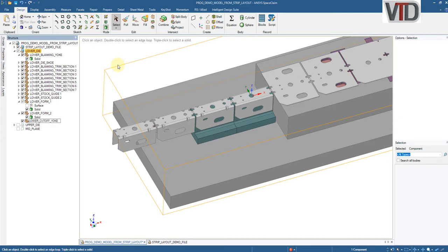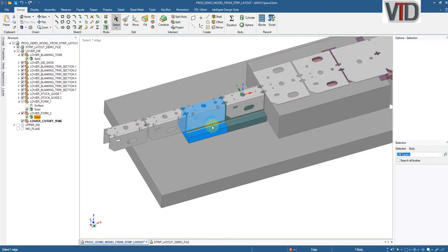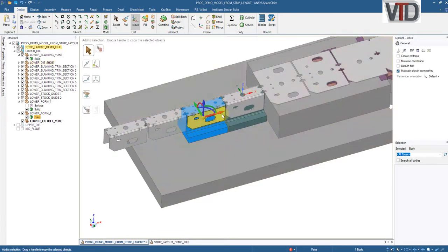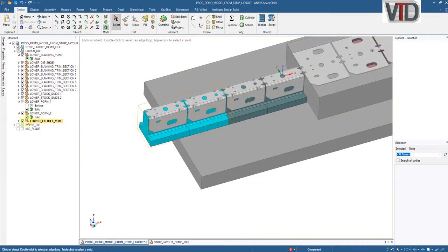It's going to hold a trim section. Then we're going to triple click this geometry and move it holding the control key. Oops, 7.5, not 7.52. Then we hold control and move it again another 7.5. And we've got two solids in there.